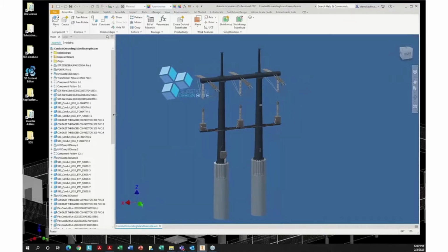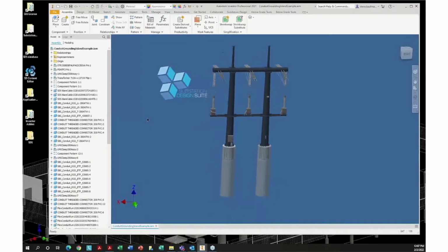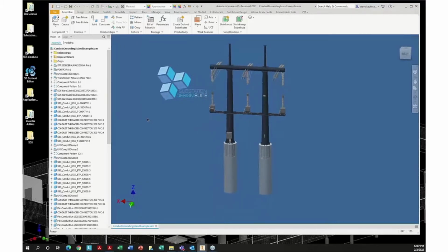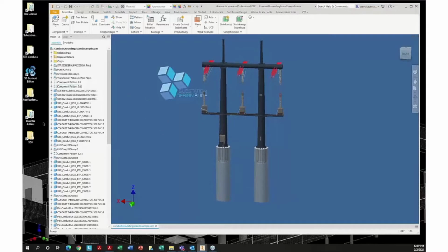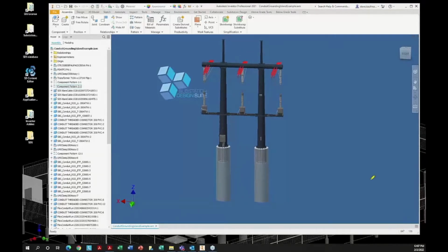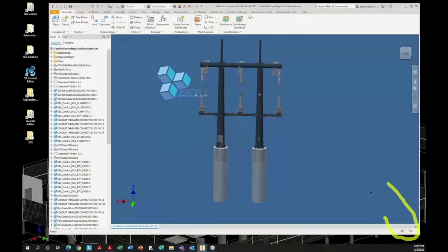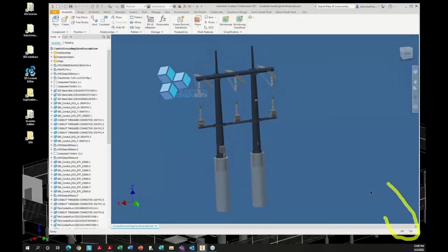I often talk about island subassemblies. They should be as populated as possible. You can see down at the bottom here I have 136 components in this island subassembly, and 847 occurrences just in this one island. If we're going to populate fully, we want to think that way. If I add 136 components to a larger model, I'm going to get lost in that model.